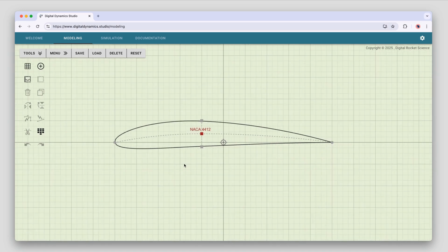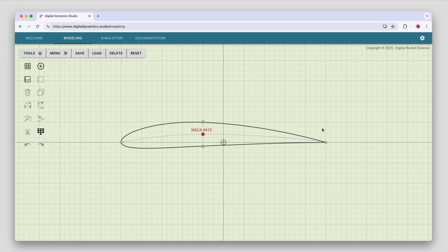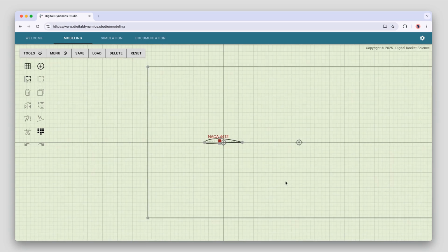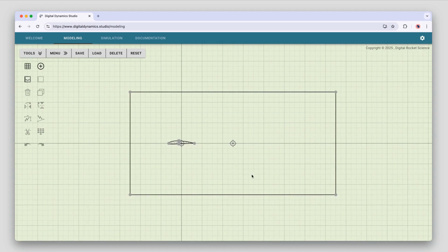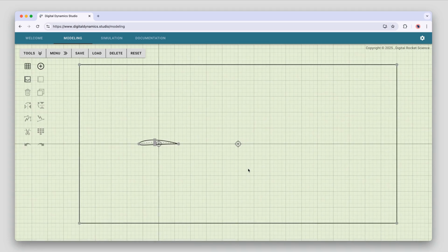But by default, in a simulation, you have the object you're simulating flow around, which you see right here, which is the airfoil. But you need to tell it where to model the fluid around the airfoil, and that's the outer domain. What you see here is that rectangle. That kind of limits where the simulation is going to happen. We're going to be simulating fluid flow within this box here, basically.